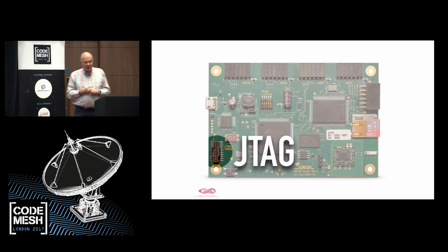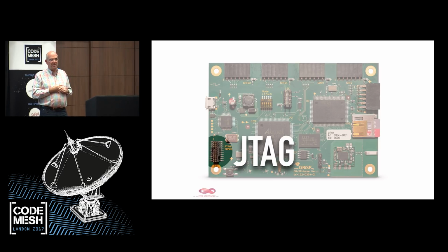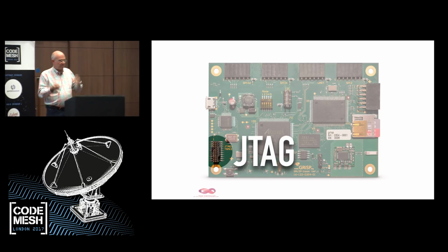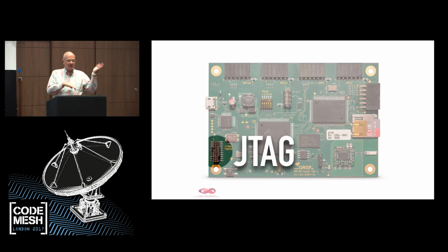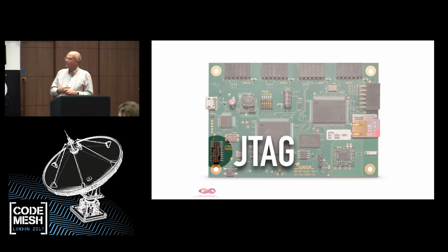There's also a real JTAG connector there, because the OpenOCD JTAG is kind of limited. And if you have a real JTAG debugger plug, which costs about 2K if you have a good one, then you can do much more things even. You can configure all kinds of things, and it's much smarter. And you have a backtrace in the debugger. You can actually see after the crash how did we get here? Which is very, very useful sometimes. So that's basically the parts of the hardware.